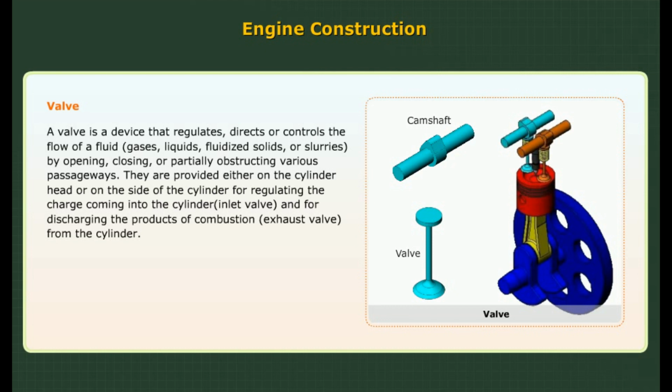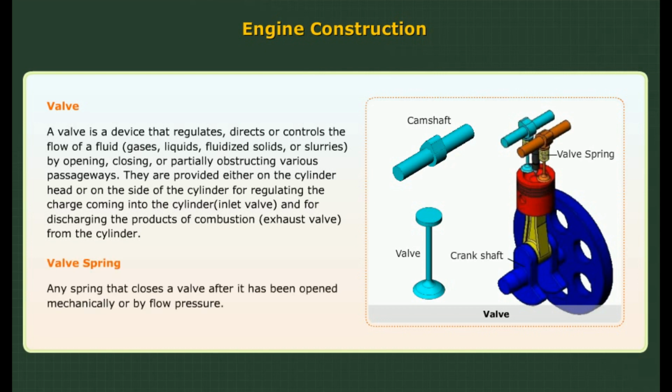They are provided either on the cylinder head or in the side of the cylinder for regulating the charge coming into the cylinder, inlet valve, and for discharging the products of combustion, exhaust valve, from the cylinder. Valve spring. Any spring that closes a valve after it has been opened mechanically or by the flow pressure.